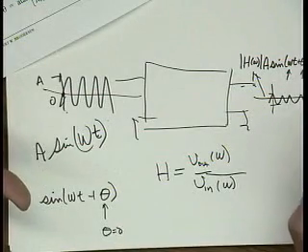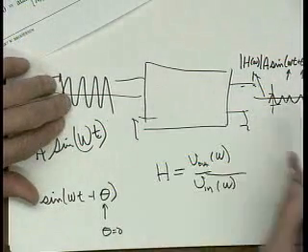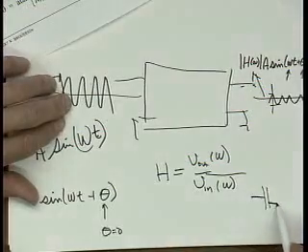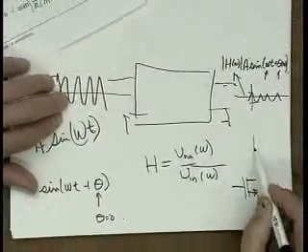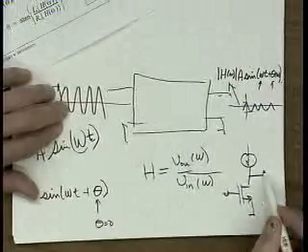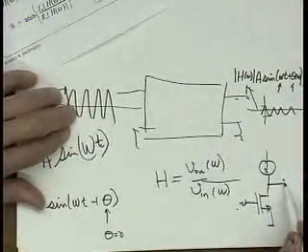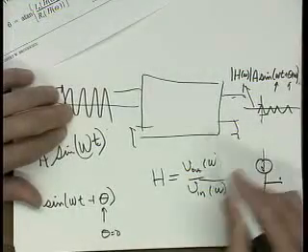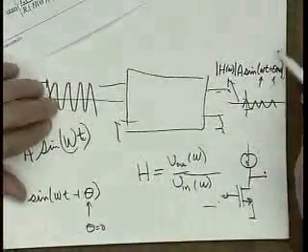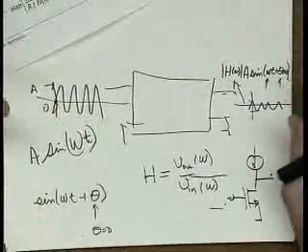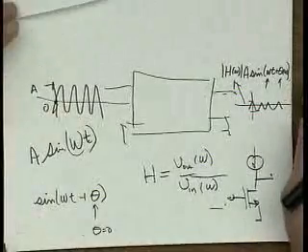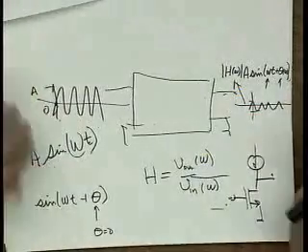It's not very important, actually, if you just have an open loop amplifier. If we just had a common source stage and some current source, and we calculated the input to output relationship, the phase shift wouldn't be very important to us, okay? It's when we close the loop, when we put feedback in this thing, that the phase shift becomes very important. So we will calculate that because it's going to be important to us in the future.